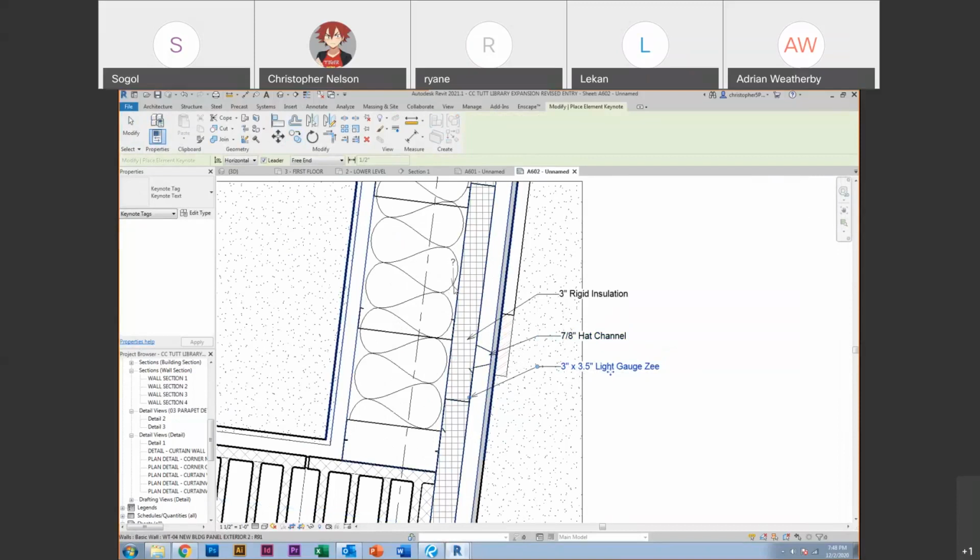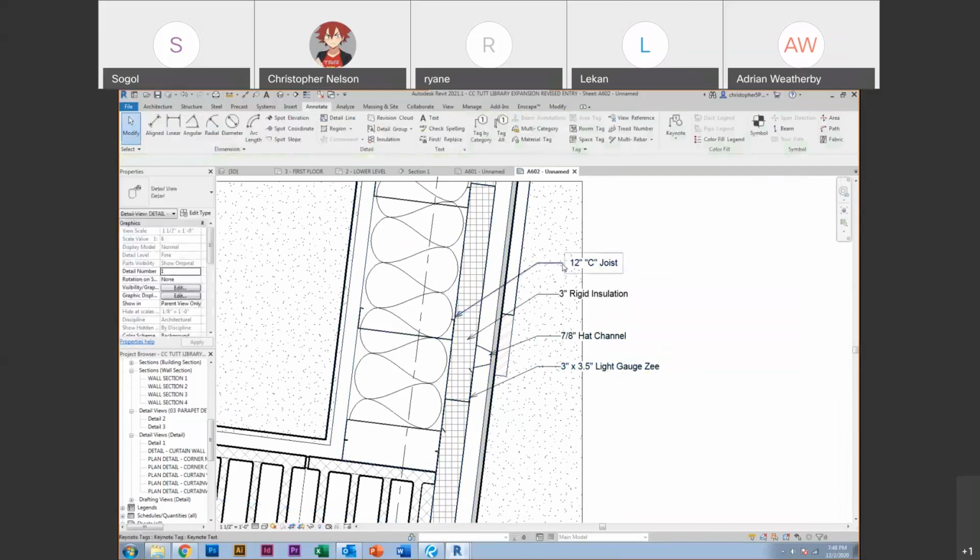I just missed how you did that. I was going to ask you again what the toggle was that you turned on that allowed you to put those descriptions there. So this is all standard out of the box Revit, but keynotes, right? If you go to Annotate, come way over to the right, you'll see Keynote Element. You can do keynotes by element, material, or just user-based.